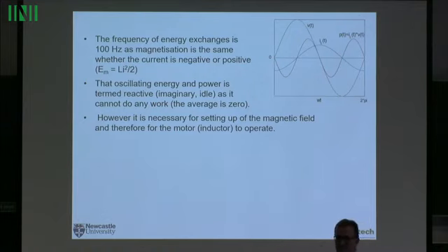Reactive power is needed in networks because you need coils, and without coils your motors wouldn't work. If the network was purely resistive, you wouldn't have reactive power. What is a resistive network? A resistive network means wires have no inductance or capacitance, straight wires. As long as you have coils, you immediately have inductance. Okay? And of course, you have AC, we'll come back to it. Basically, that phenomenon exists in AC networks only.